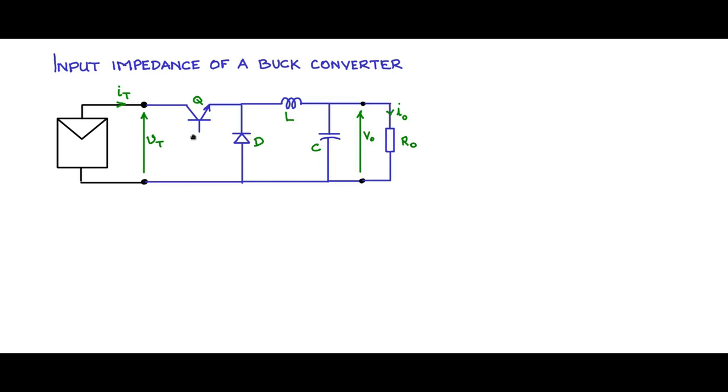So this is the buck regulator circuit connected to the PV module. In the boost converter, connecting a capacitor across the terminals of the PV panel is not mandatory, though it will be helpful. But in the case of the buck converter, connecting a capacitance here is mandatory. It has to be connected. I will connect that later after discussing why. For now, let us understand the operation of the circuit and try to find the input-output voltage relationship, input-output current relationship, and the input-output resistance relationship.